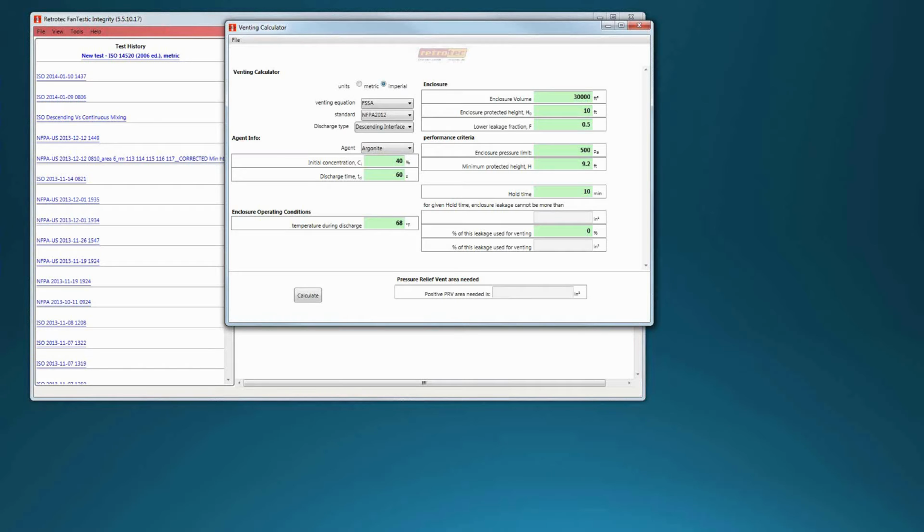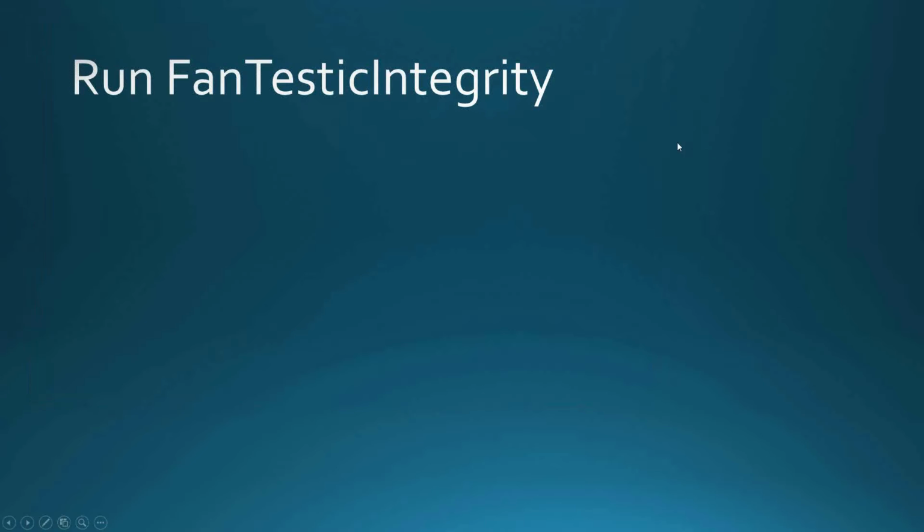And a 500 pascal wall, 2x6, sheetrock on both sides, pinned to the floor and pinned to the slab above, should have no problems holding 500 pascals. So as far as the minimum protective height is concerned, let's put that in at 7.5. That's pretty common. Oops.